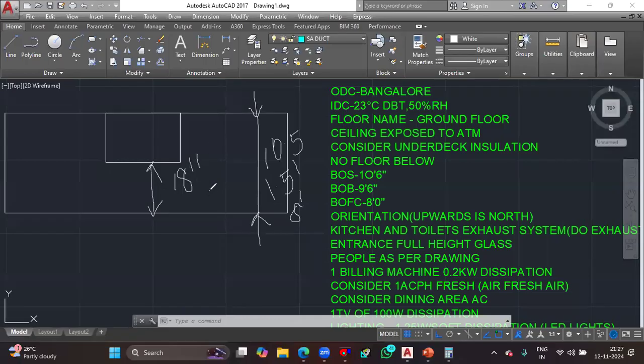In order to find out the height, you need to start with other aspects, such as insulation. So if they provide some kind of insulation, obviously we need some clearance spaces. So if you take 1 inch clearance on both ends, like here and here, it should be a much lesser distance. Then the duct height will become 16 inches. But 1 inch is not enough for us, isn't it?